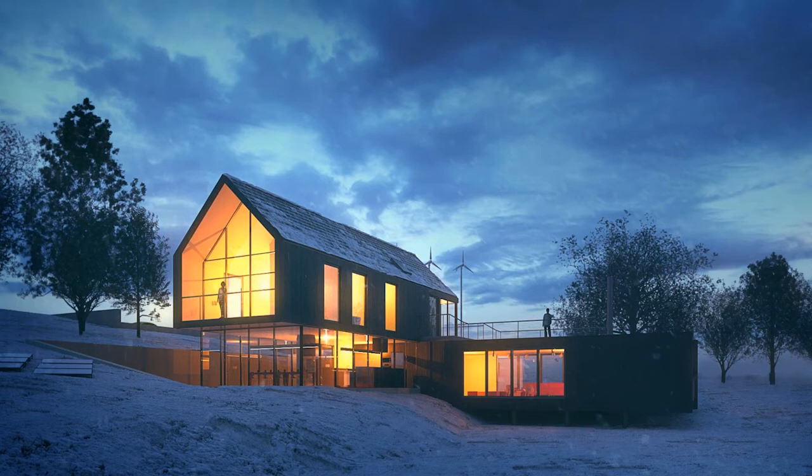We've bumped up the actual lights inside of Revit specifically, because we're using Revit native lights, and so we've changed the lighting to be a little more orange, a little warmer. Of course, we're taking the lights that exist in your current model and translating those to IES files automatically behind the scenes. But one of the great things you can do in V-Ray for Revit is select an individual light or light fixture and override the IES file, and we'll pull that through in the renderer itself. So as you make the change in your BIM, that updates in what we pull across.